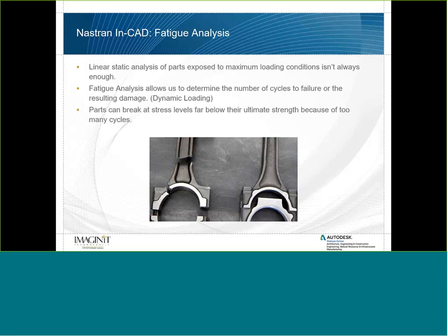So we'll need to apply our material data specific to this analysis, and we'll also have to apply our load in a fashion that is dependent on time, or is loaded in a way that applies a load and then reverses the load to indicate tension and compression.